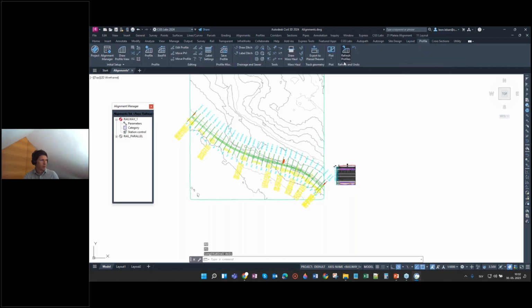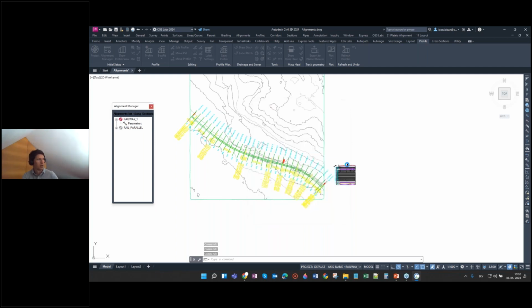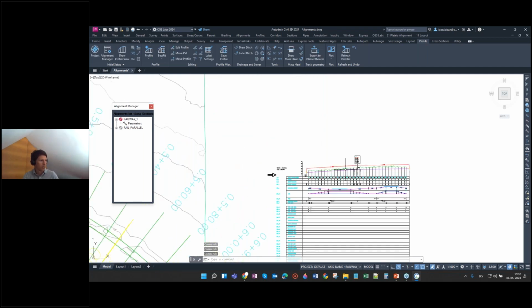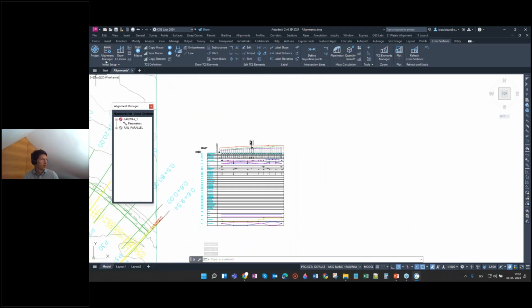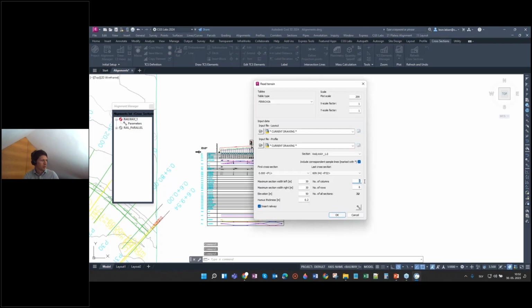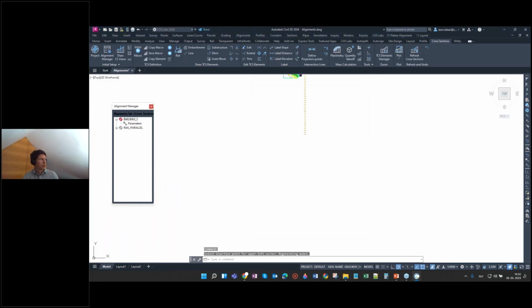We go to our profile, we refresh the profile, because before I went there directly, which is also a possibility, and we get the 3D rails in our layout anyway. But now we have the cross sections in, and we can simply draw our cross sections and go into it with all the details needed for the designing, as we saw in the picture before.